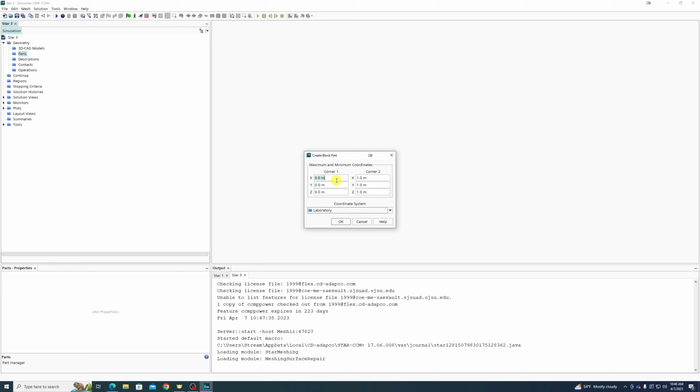So it's going to start, I'm going to say 4 meters upstream. We're going to call the start of our body x equals 0. The domain is going to start at y equals 0, which is, again, in line with the bottom of our body, which is going to be a double wedge. Z equals 0, that's fine.